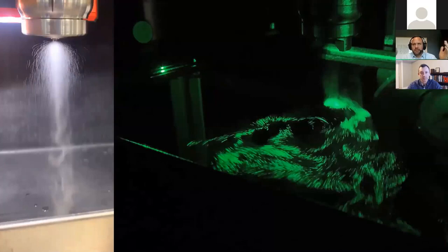Typically, we can see a 10 liquid, 10 air differential, and if you get outside of those bands, you run the risk of vapor locking or having some kind of challenges within the process. But again, it definitely depends on the liquid that you're spraying, and that's where the lab testing, benchtop testing, really comes in very handy with what you're trying to achieve.